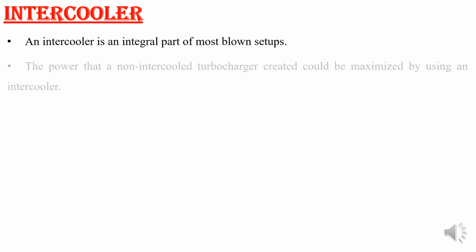So the power that a non-intercooled turbocharger creates could be maximized by using the intercooler, because without an intercooler, if you send that pressurized air at high temperature, the density of the air once again comes down, and there won't be much power output increase. Whatever you expected, it may even decrease your power output. So an intercooler is necessary for a turbocharged engine.